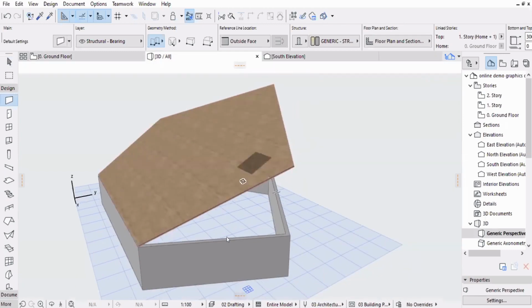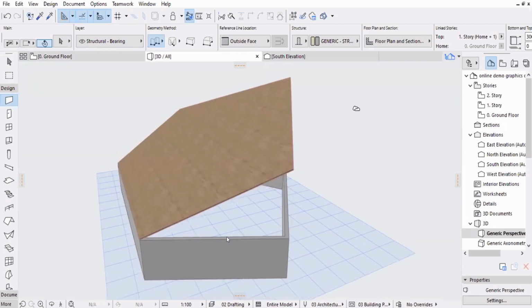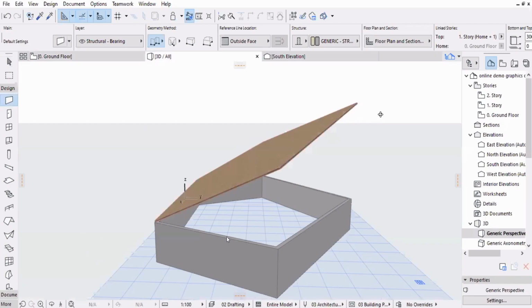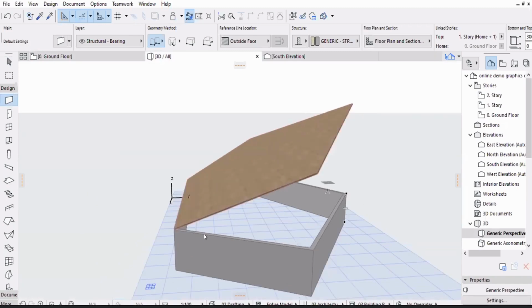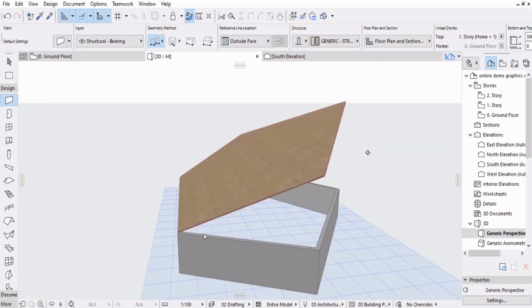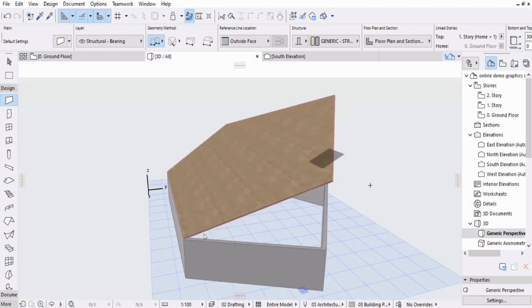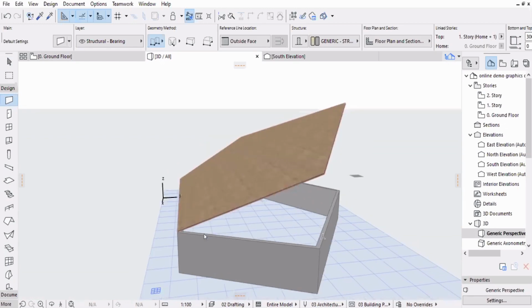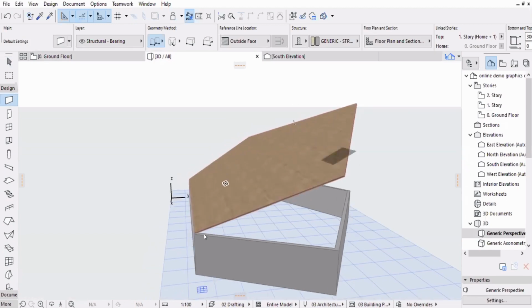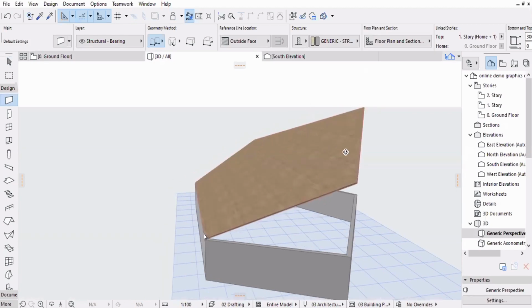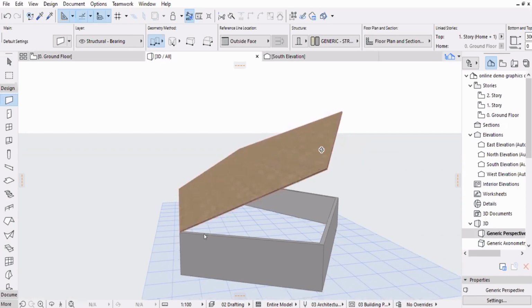You have to draw these walls, all of the height of this wall, well above the roof. So, for example, if this height is 10 meters, just imagine this is 10 meters, then the wall heights will have to exceed that 10 meters. It will have to project above the roofs in order to then cut that portion of the walls going above the roof. So basically, it's a two-step process. First is to draw up the walls well above the roof, so that it cuts through the roof. Second step would involve using this roof as a plane and cutting that extra portion of the walls. Okay, all right.